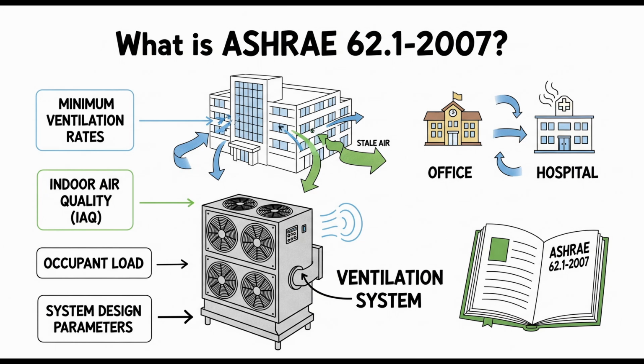Right. This is important, especially in humid climates or certain building types. The standard requires that mechanical systems that dehumidify must be designed to keep the relative humidity in the occupied space at or below 65%. 65%? Why that number? That's generally considered a threshold to significantly limit mold growth on surfaces and within the HVAC system itself. It reinforces that point about avoiding continuously wet surfaces anywhere in the system.